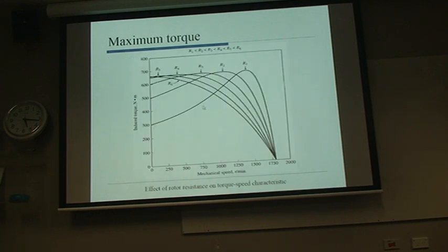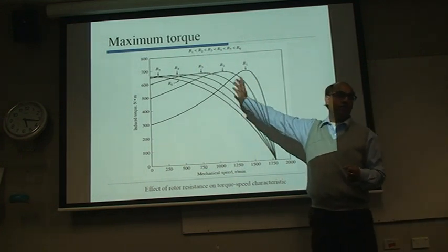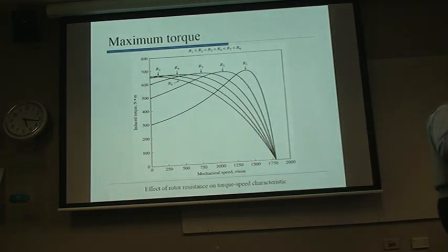So that's what. So earlier days, when drivers like inverters were not available, lot of research was done on induction motor because people want to control the speed. So that was one of the method by introducing resistance in the circuit. And that was not possible in the cage rotor because cage rotor, the winding is short circuited. On the slip ring, you can introduce external resistance. So this was done for the slip ring induction motor.